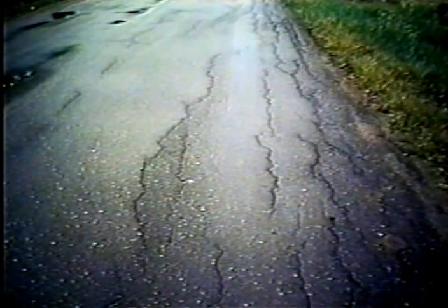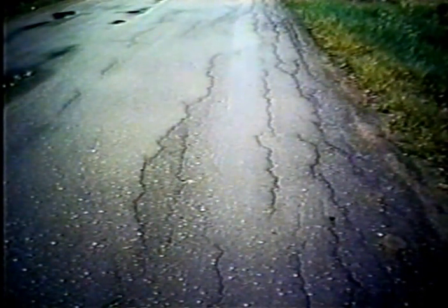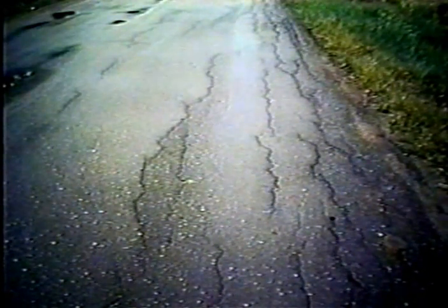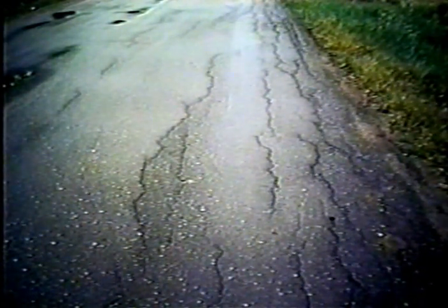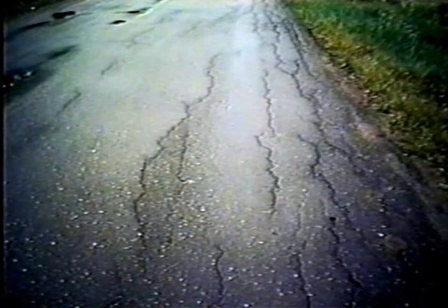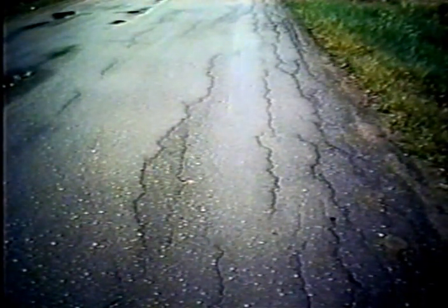rutting evident, it had fairly open, wide, ravelled longitudinal cracks, saying that we needed to rebuild and strengthen this pavement, not simply put a thin asphalt overlay over it. This is an example of what not to do. We just don't have enough money in our maintenance budgets to make mistakes like this. Hopefully, if you do a good job of looking at the distress and thinking about the causes of distress, we can do a better job of selecting the appropriate maintenance or rehabilitation procedures.